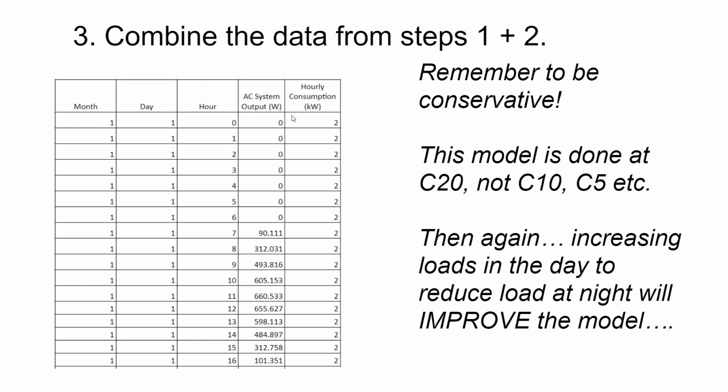What we'll learn is that when you discharge a lead acid battery and you drain it by 50% or more, it's going to lose about 2/3 of its storage capacity. Unlike lithium ion, which still does have a declining return the faster you discharge it, but it's not so dramatic.